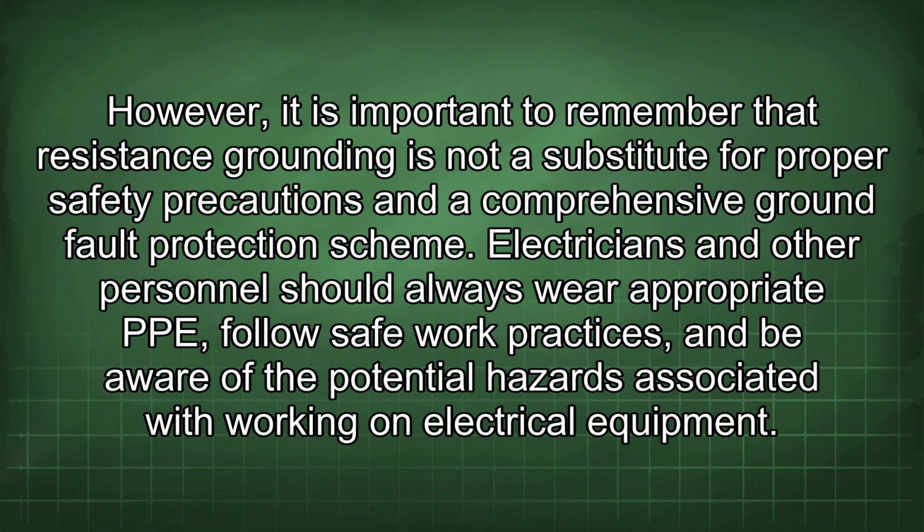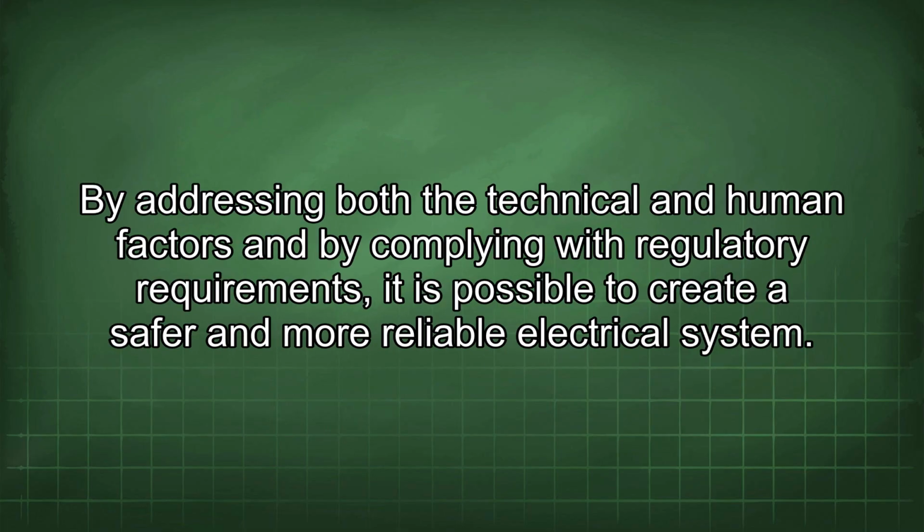However, it is important to remember that resistance grounding is not a substitute for proper safety precautions and a comprehensive ground fault protection scheme. The electricians and other personnel should always wear appropriate PPE, follow safe work practices, and be aware of the potential hazards associated with working on electrical equipment. By addressing both the technical and human factors and by complying with regulatory requirements, it is possible to create a safer and more reliable electrical system.